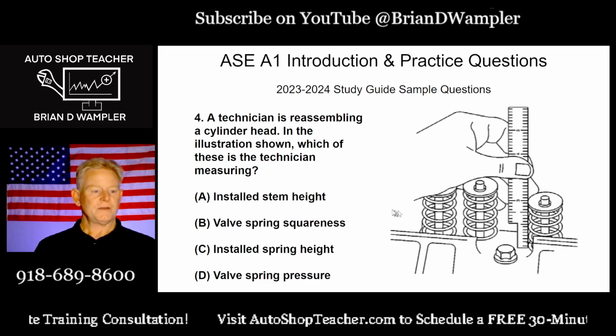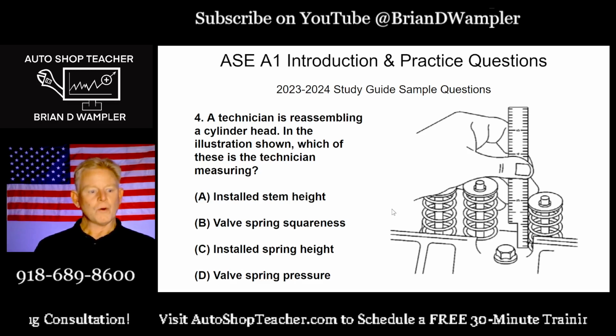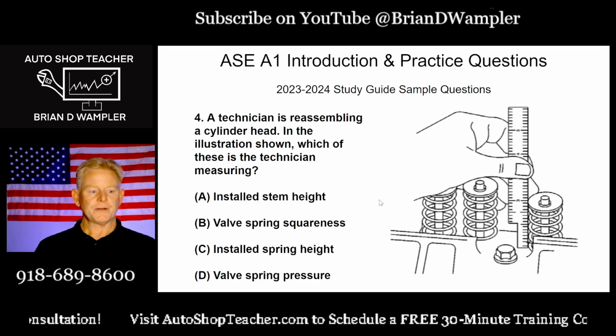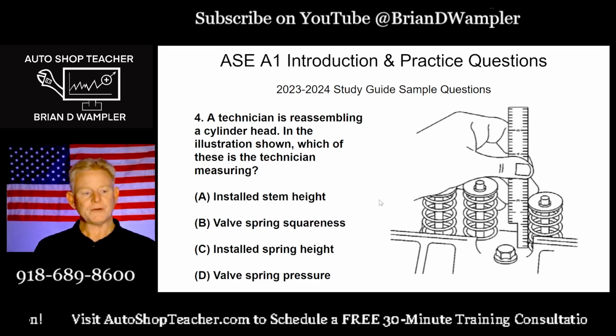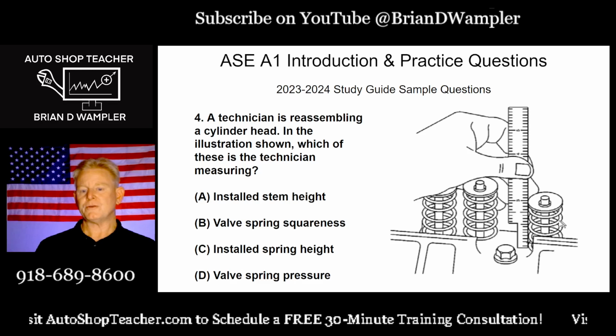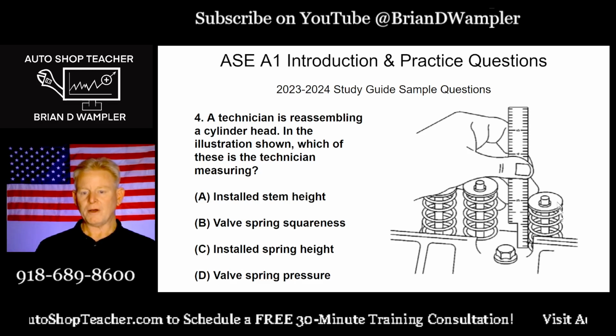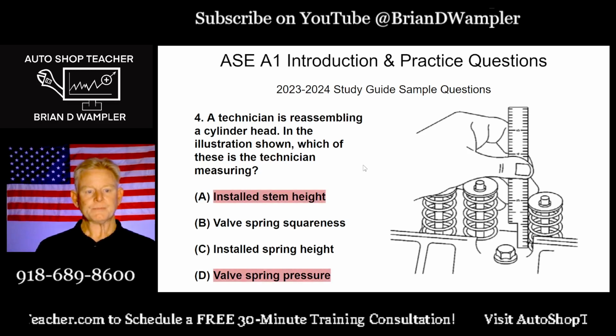Okay, is he measuring the installed spring height? Or is this technician measuring, and I don't mean to keep saying he or she, are they measuring the valve spring pressure? The amount of pressure that this spring is applying between the retainer and the cylinder head. Okay.